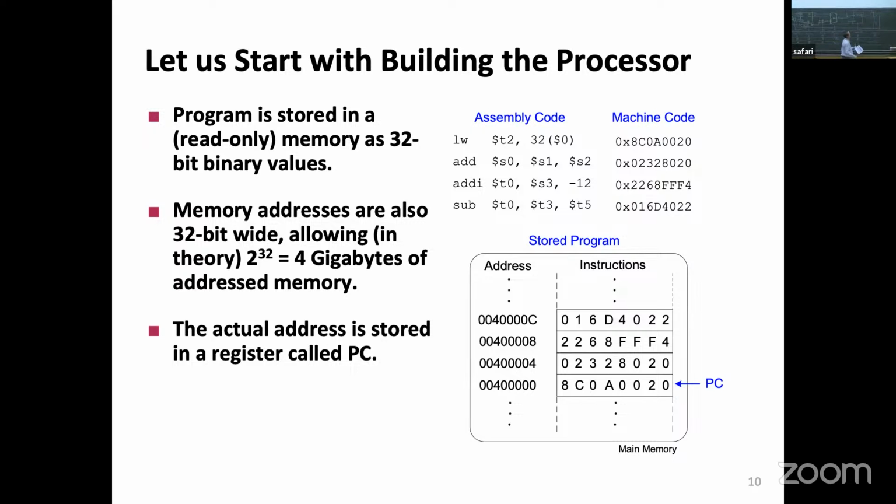We don't read back anything. So I don't care if we read back the ALU result or this. It could be anything that they choose, because we are not reading from the memory. If we are not reading from memory, it doesn't matter. We are not going to write anything back here. Just like we didn't care what the address was. Now, the important distinction is, this is not undefined. It's just that I don't care. When you write code and synthesize it, the synthesizer will pick something. They could pick 0, they could pick 1, whatever makes their life easier. Remember at the beginning, when we were doing combinational logic optimizations, we said we can take advantage of the don't cares to make our life easier. So this is what will end up happening there.